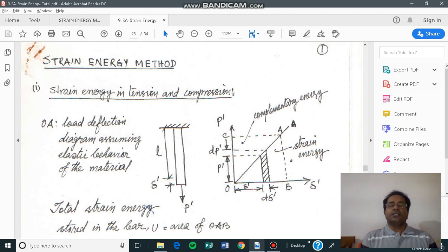So if I imagine a beam, when it comes with a set of external loads, we all know it deforms, and also it develops some internal forces in the member. Those internal forces are represented in the form of axial force, bending moment, and shear force. These internal forces with the deformations develop some strain energy.